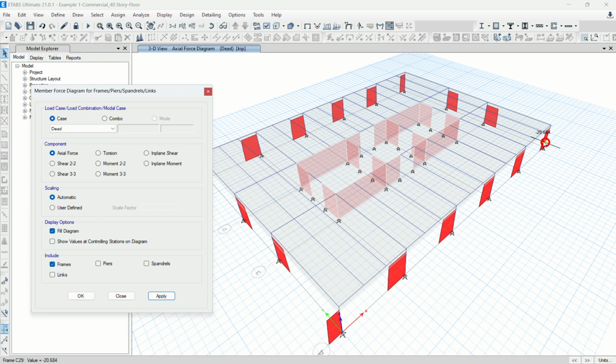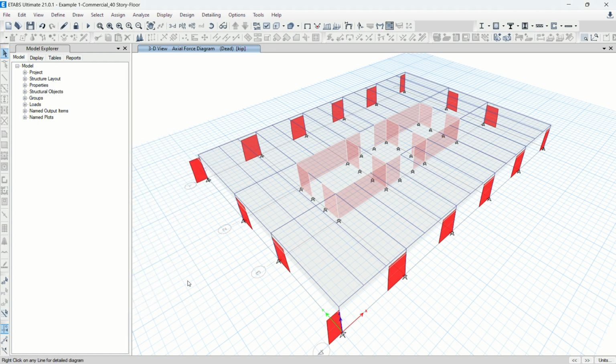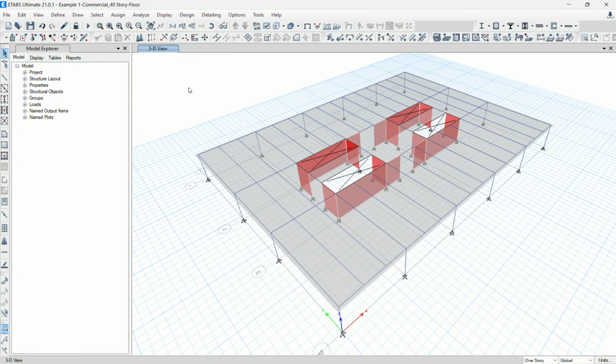You see that the column axial force represents column reactions based upon dead load, which is self-weight, and is based upon each column's own tributary area. You see the actual forces vary. So this model seems ready. So I'm gonna unlock.